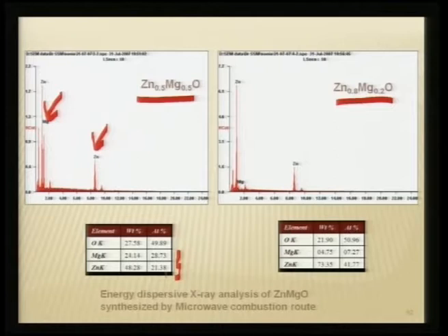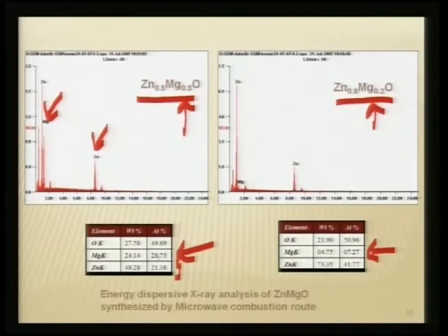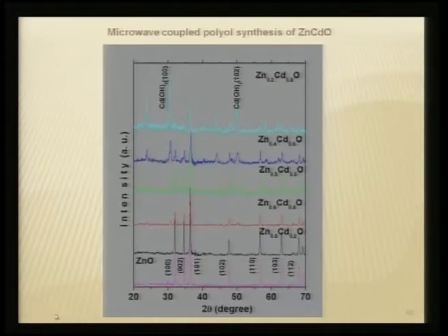Therefore, there is some limitation to the doping effect. If you are thinking of a 20% doping, you can see only 8% is doped. If you go for 50% doping, you see roughly 30% of magnesium is doped. So, there is still an inconclusive issue revolving around the relative stoichiometry, but nevertheless we see this is the maximum that we could go, maybe up to 30% of magnesium can be doped outright because of this exothermic process.